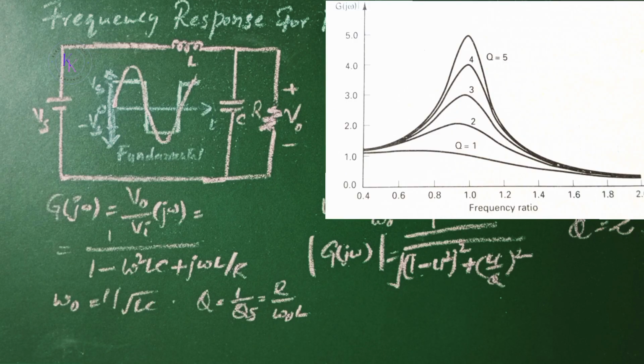Thus, the output voltage response is a function of the load and can be very high at no load if the operating frequency is not raised, but the output voltage is normally controlled at no load by varying the frequency above the resonance. The current carried by the switching devices is independent of the load but increases with the DC input voltage. Thus, the conduction loss remains relatively constant, resulting in poor efficiency at light loads.